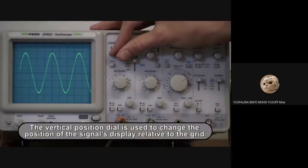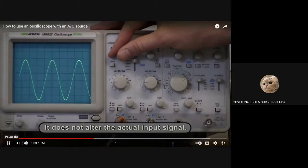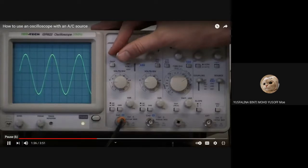The vertical position dial is used to change the position of the signal's display relative to the grid. It does not alter the actual input signal. Okay, so the position means the graph can move up and down. Why do you need to move up and down? You can adjust it to make sure you can read the graph easily. So you can move the graph up and down according to the grid given.